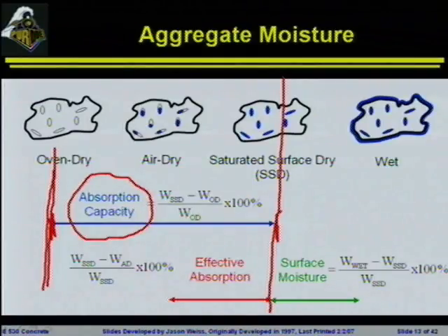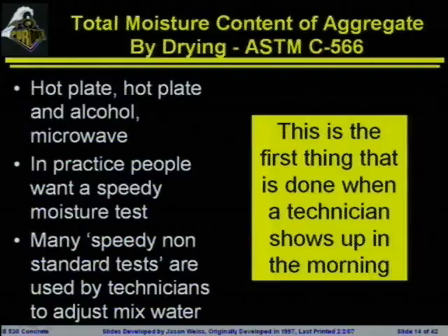The effective absorption is typically going to be determined for the air dry case, where we've got the saturated surface dry minus the weight of the sample over the weight of the SSD. And surface moisture, we're typically going to be talking about the wet weight minus the weight of the SSD over the weight of the SSD. All right. As I mentioned, typically these are going to be done fairly quickly.